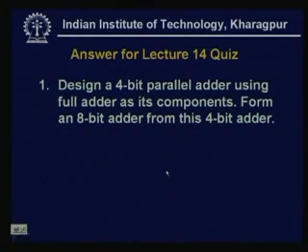Now, one quiz question for today's lecture. Design a 4-bit parallel adder using full adders as its components. We have already read the half adder circuit, the full adder circuit, and a variety of them. Now we will treat the half adder or full adder as a module, just like gates.